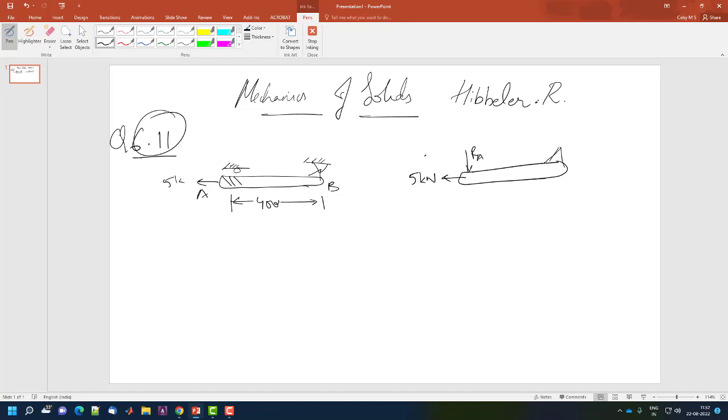Let me just consider this as a single body, and here there will be RYC and RXC in the x and y directions. I have only given a y direction force at A because there is a roller over there, so it will only give restriction in the normal direction.